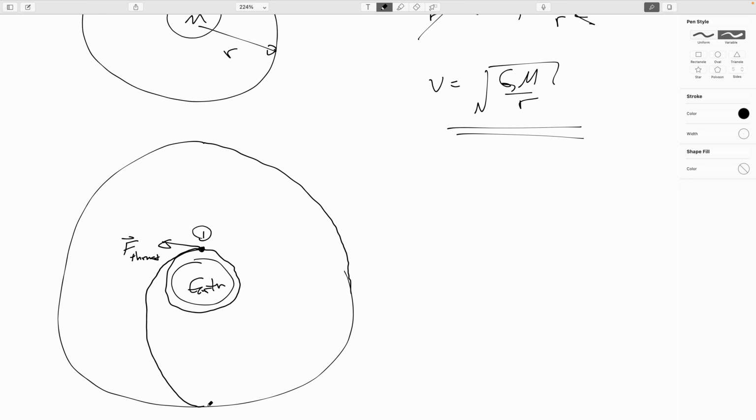And then the idea is you put it into an elliptical orbit, like so, but you'll notice that I drew a dotted line. This is because sometimes you let it go more than once, but a lot of times when you get to the top half of this elliptical orbit, this is burn number 2. Again, pointing tangent, so you're burning in the direction you're going, and you do the burn to get yourself up into this higher circular orbit.